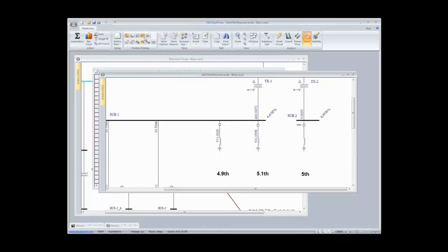Okay, I decided just on purpose to show the root sum square current into each of these filters. Look what it is for one, 220. So if I put this filter online, it really should be 220. I mean, they should be drawing about the same amount of current. Maybe they would even be sharing some of the fifth harmonic, so it might even drop a little bit.